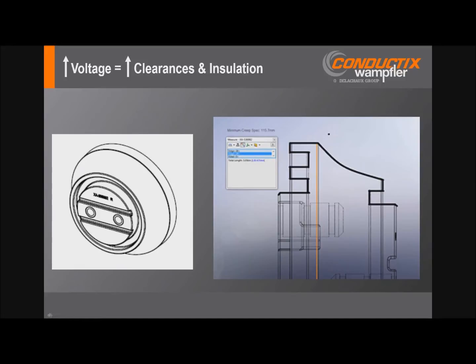Lastly, increased voltages have diminished benefit for all but really the largest monorail systems. And although power losses, I squared R losses, decrease as voltage increases, thicker insulation, the greater electrical clearances, and the likelihood and consequences of stray currents associated with higher voltages typically offset the power savings advantages of operating at higher voltages. So we just don't typically see monorails, or maybe a few at 1.5 kV larger systems, but generally they're in the 700 volt DC nominal range.